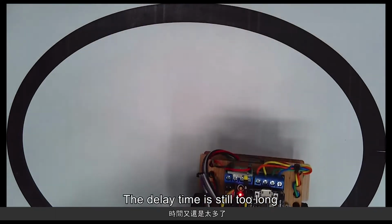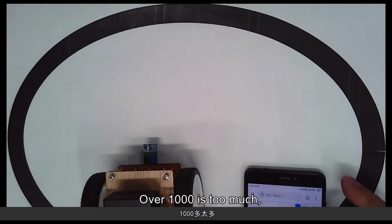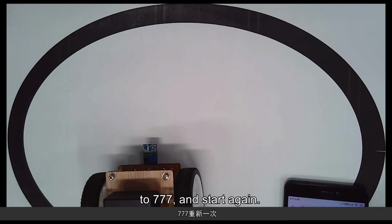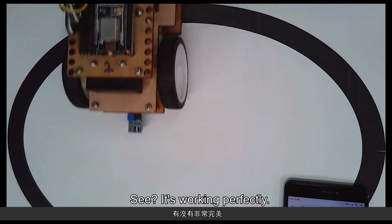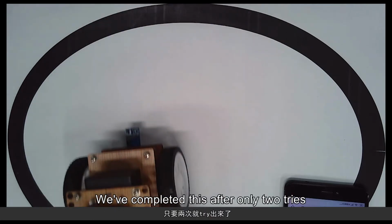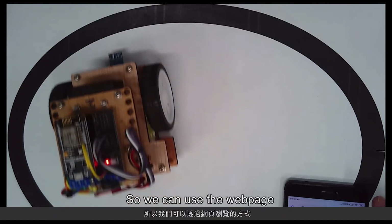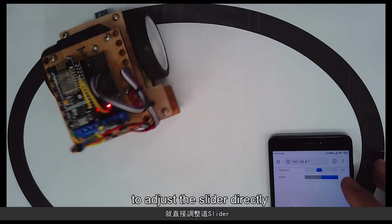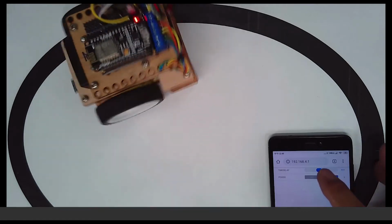The delay time is still too long, so we'll shut down the vehicle first. Over 1000 is too much. We'll adjust to a lower value, 777, and start again. See, it's working perfectly. We've completed this after only 2 tries, and it's easy to make modifications right away. So we can use the web page to adjust the slider directly and make more precise control of the rotation angle.